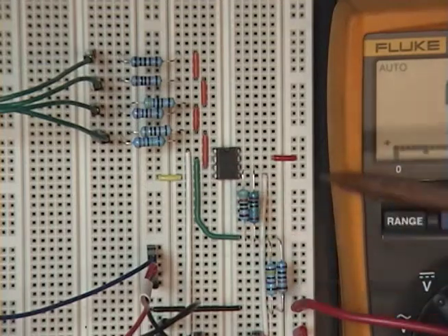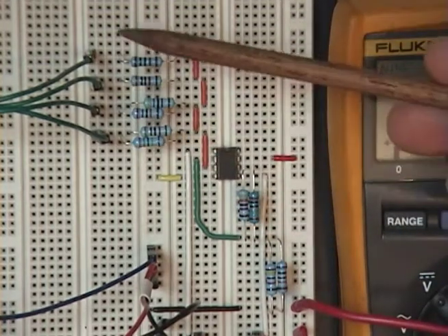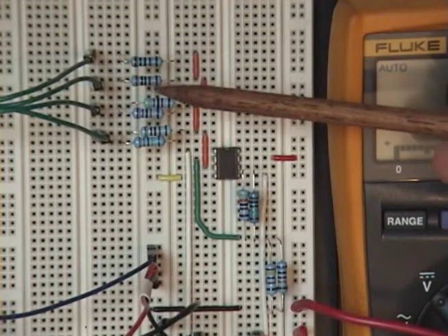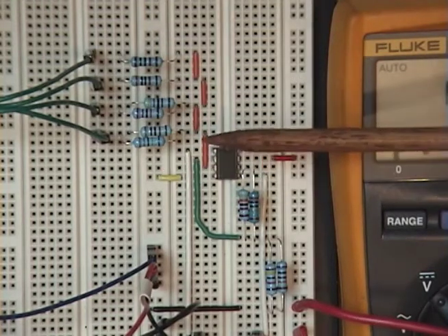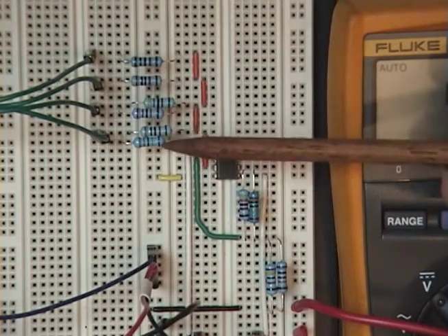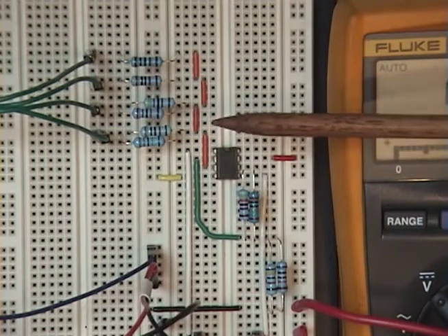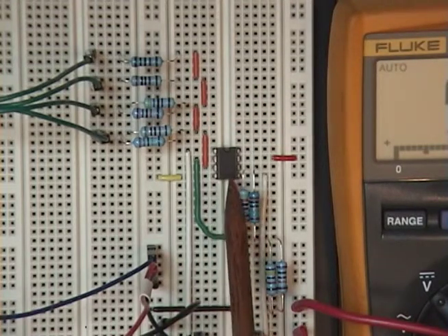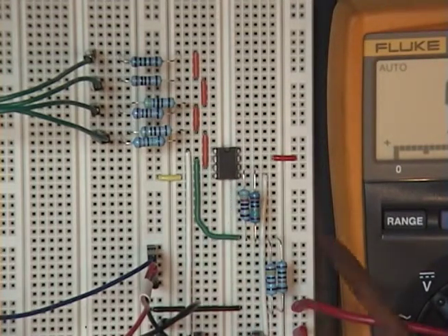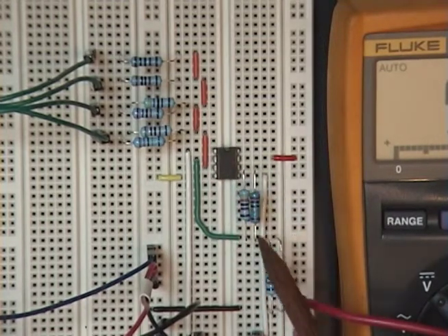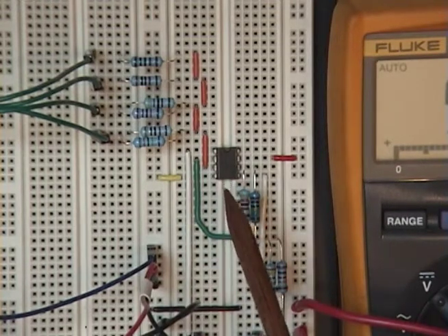Here I have the circuit we just designed doing a weighted sum of 4 inputs. In this actual implementation, I'm using resistance values of 10K, 20K, 40K, and 80K. Notice that I had to implement the 40K and 80K with resistor pairs, since those aren't standard values in the E24 series of resistors that I have available. Here we have the venerable 741 op-amp. The output of the resistor ladder comes into V+ here, and here's the feedback voltage divider off the output, with the feedback going to V-.